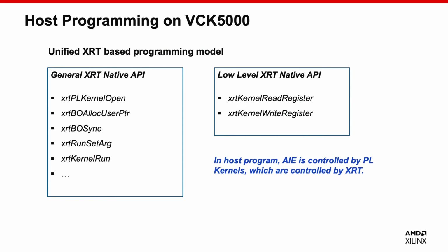Now briefly introduce the host programming. After you have finished all the hardware building, you could use the XRT native API to finish the host-side programming. For the current VCK5000 platform, the host programming model is the same as other traditional accelerator cards. You just need to program for the host CPU. No A72 CPU programming is needed.